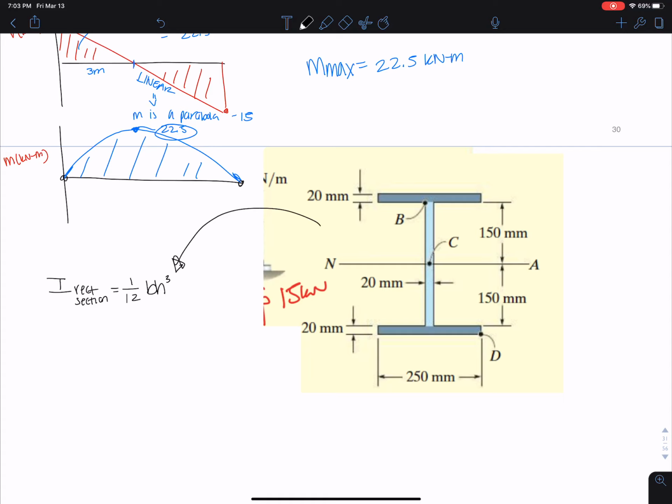And that's a really easy formula to memorize because I don't want to have to memorize a bunch of different types of moment of inertia formulas or derive them from dx, dy integrals. So I want to stick to this if I can use it. And I can because all I have here really are just 3 sections. This would be section 1, and then section 2, and section 3, that are all rectangles. But the trick about moment of inertia is this is the moment of inertia of a rectangular section that passes through the NA. But you can see here that only section 2, I'm going to put it in red, passes through the NA. So this formula is only really valid for this section in red.